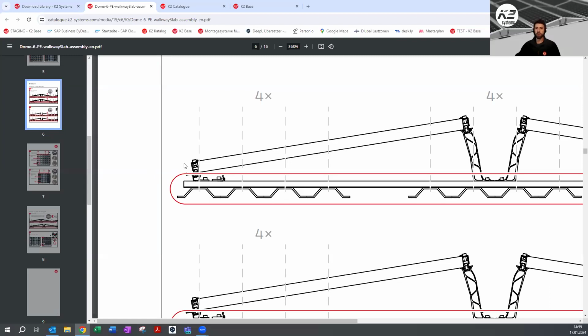Thank you. Base is only, and that's very important to know, we will get to this point later, but I can tell you already now, Base is calculating the extra ballast. If you have 5 kilos of extra ballast which is needed, but you are using 20 kilo stones and you place another stone, then you of course have more weight on the roof as well. Base as a program only calculates with the amount which is needed extra. And that's very important to know.